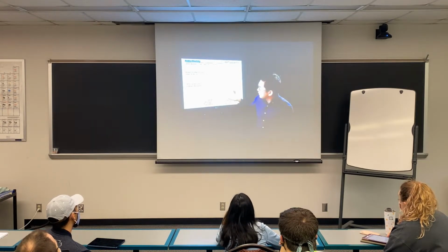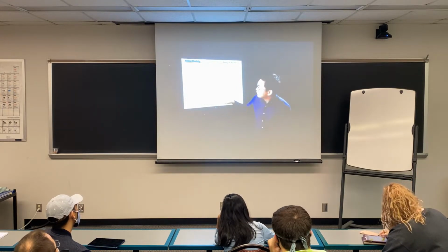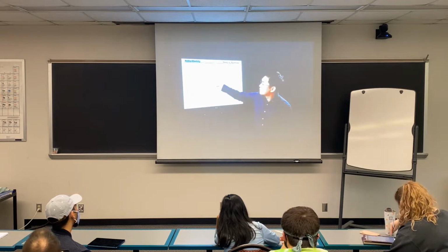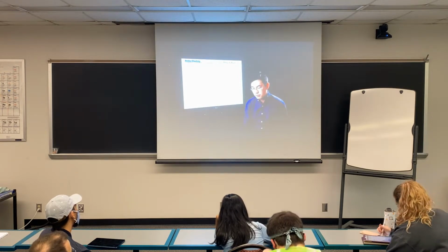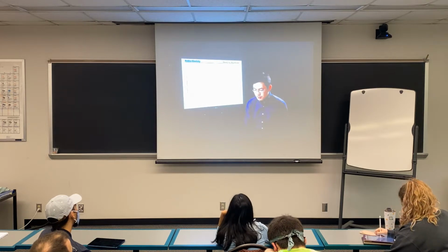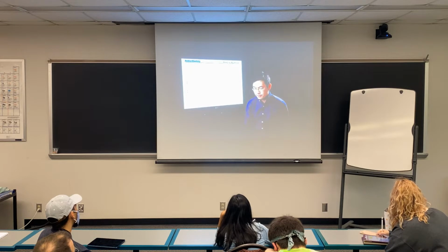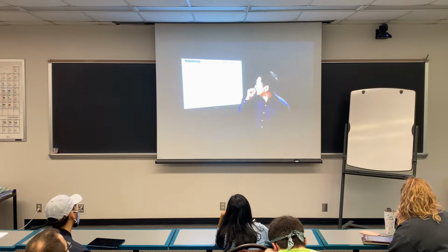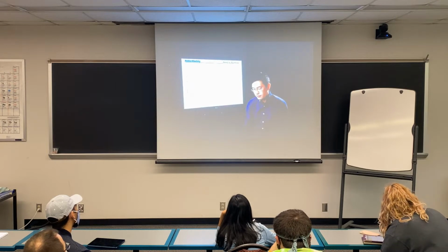Based on the theory we had, people were able to do an example test where you take a rubber and plot tensile or compression force with respect to compressional extension, and you can see the mechanical response of the material. You can tell the theoretical curve is shown by the solid line, while the dashed line linked between the dots shows the experimental data, and there is pretty much good agreement between your theory and your data.